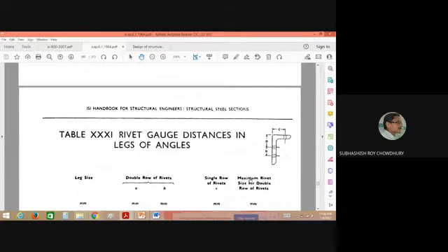And when you design the steel structure, you must remember that there are some standard steel sections that you have to use. There is no scope to give any arbitrary thickness or arbitrary width of any section. So some standard sections are there, and you have to use that. If section A, for example, you have taken and you have checked, and section A is failing, then automatically you should consider another section, say section B, which is obviously higher than section A, and check whether it is safe or not. If section B fails, then you have to consider section C, like that.